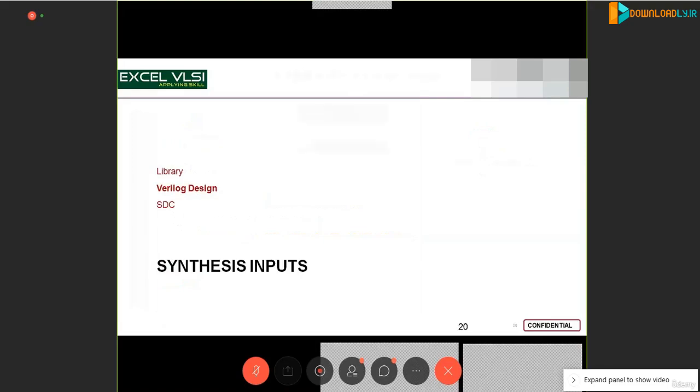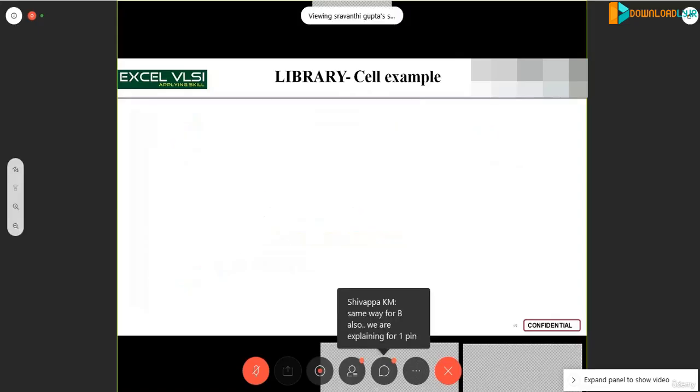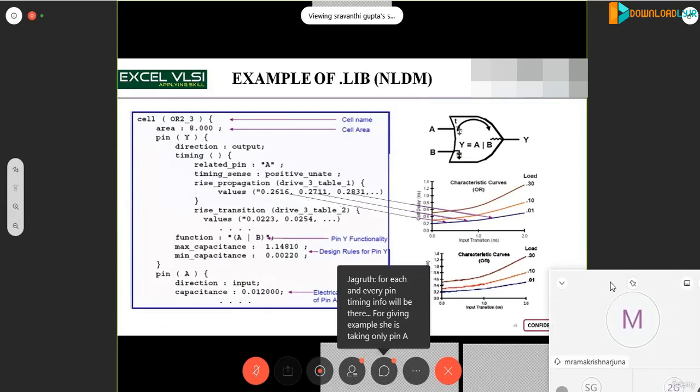Excuse me, the delay based on which methodology? Whether NLDM or CCS, how can we consider? As I told you, if you take an NLDM model, there will be fewer capacitance values. So the capacitance values will be minimum. That means it will be a 1 or a 2 value, or a range like this will be specified, max and min capacitance. Okay, but based on the gate, suppose here some buffer, for a buffer what do we have to choose, NLDM or CCS? How can we?